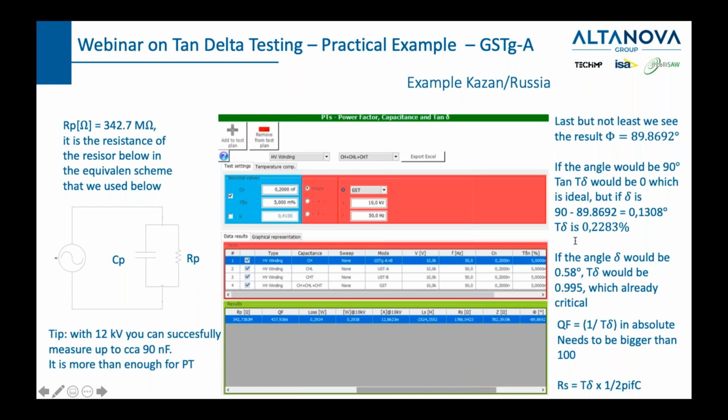Mr. Branko Čulić asks, how about measuring tan delta on dry transformers? Absolutely. You can do it on a dry transformer, you can do it on an oil-filled transformer. Any transformer can have a measurement of tan delta. It doesn't change in any way. It's simply that a dry type transformer probably will be a distribution transformer, and in that case, the interpretation of the result would be less conservative, so you could have a bigger value of tan delta when measuring and still have a good insulation.